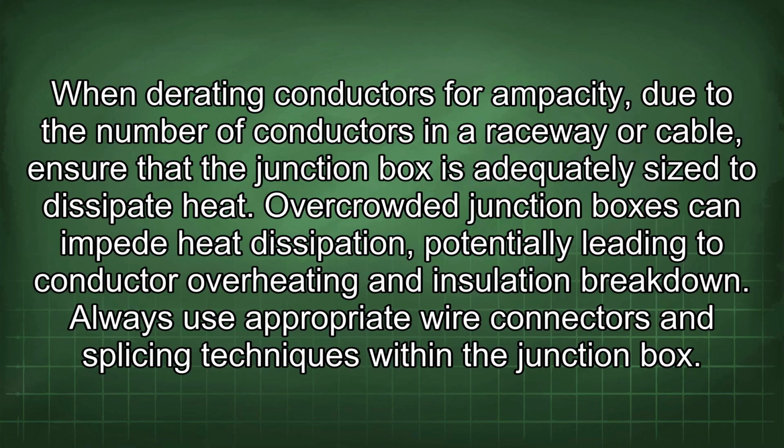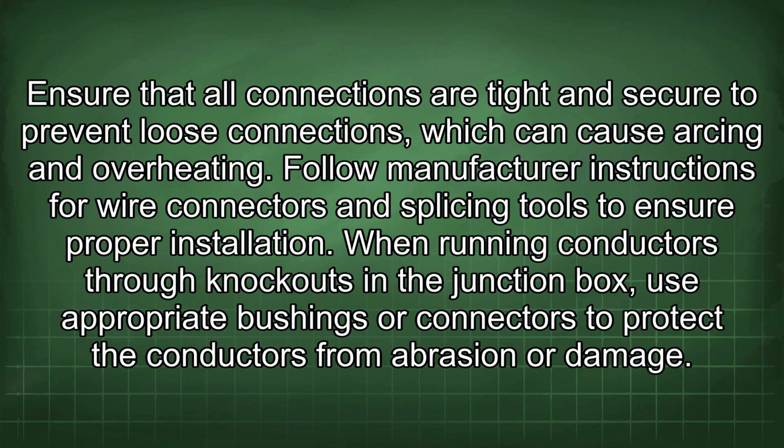Always use appropriate wire connectors and splicing techniques within the junction box. Ensure that all connections are tight and secure to prevent loose connections, which can cause arcing and overheating. Follow manufacturer instructions for wire connectors and splicing tools to ensure proper installation.